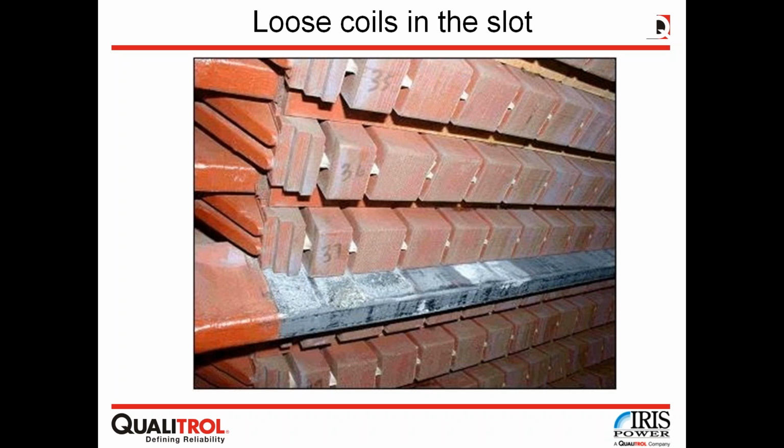Okay. All right. What sidebands does the MDSP3 look for? Many. It will be looking at one type of sideband for the analysis of broken bars, and then other types of sidebands for the analysis of air gap eccentricity. Additional slides could be provided to explain this if you get an email from the user who is asking this. Okay.